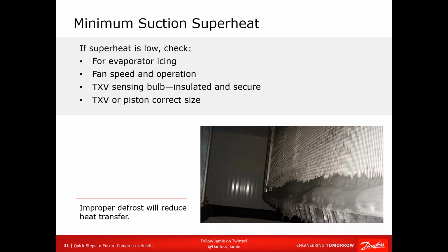How many fans do you have? Are they all running? Are they turning in the right direction? Trust me. Has somebody used the wrong speed tap? All these things need to be checked. Your TX bulb, is it insulated and secured? Is it hanging somewhere in the air? Is the sun shining on it?